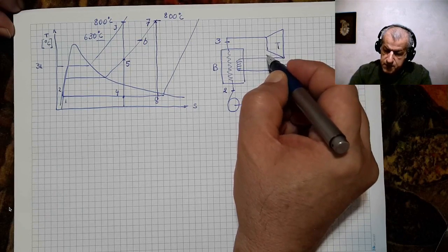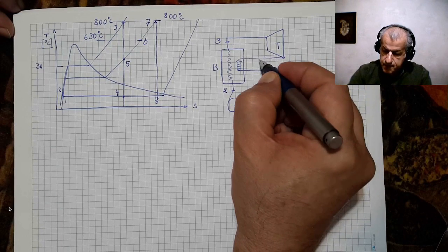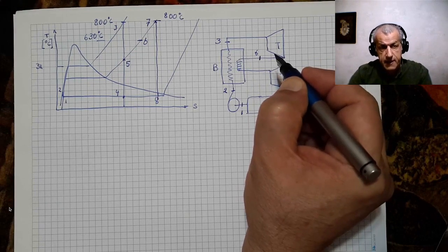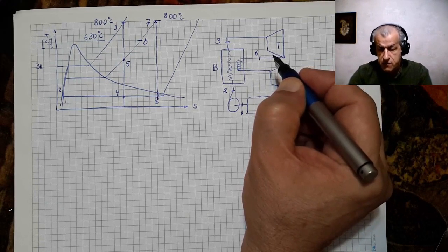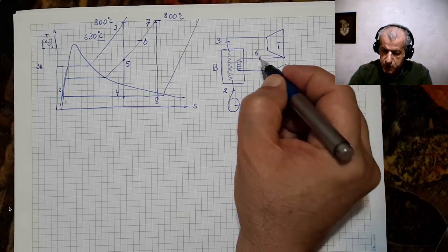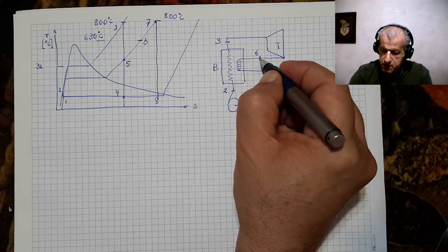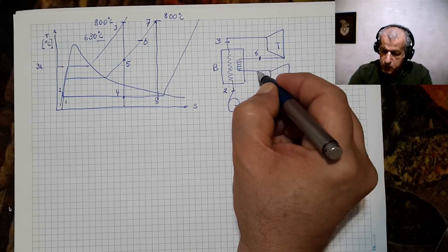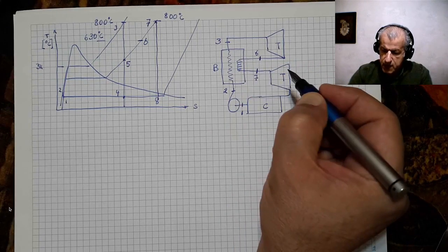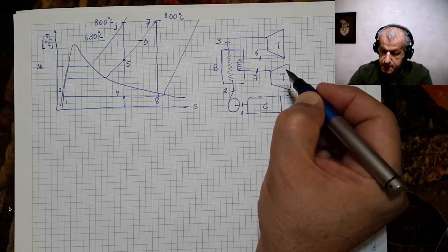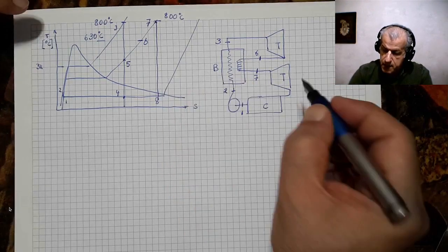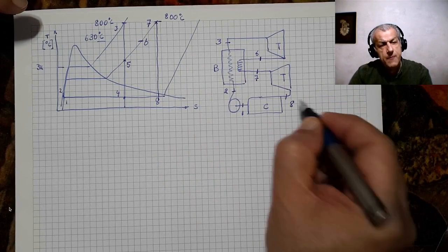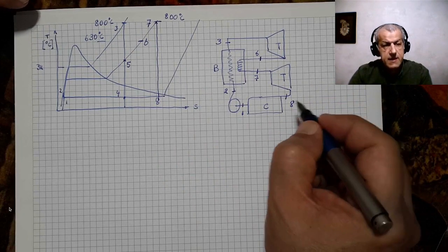This is point 6. The point 5 is for an ideal turbine, and we don't know if we have it or not, but we know that we have a point 6 where the fluid goes out of the turbine into the boiler again, and at point 7 it goes out and enters the second turbine, and out of the second turbine is point 8 and then enters that condenser.